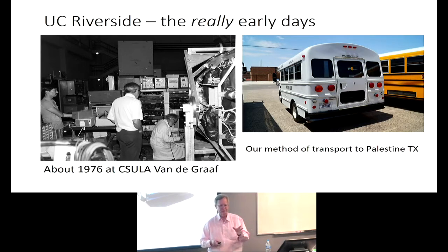This is a time when it was just becoming possible. There were not computers to fly in these packages. There was integrated logic, TTL logic, and you had to do this all within 100 watts. So it took a lot of very clever work to design a system that could collect these high-speed, microsecond-long pulses from the gamma rays interacting, and go all the way up to adding them up in different energy and time bins, forming the data stream and modulating the FM signals and sending the data back. It was quite a job to do that. And so he would do this design, the whole system, on about a 4-foot by 6-foot panel in pencil, and then break it up in pieces, and graduate students and technicians would build them all.